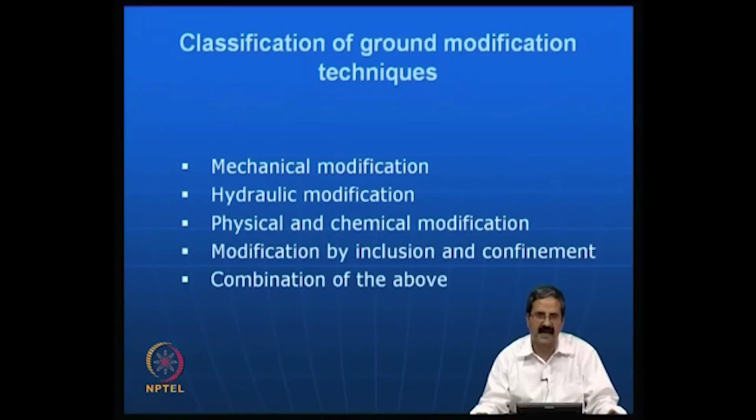The liquid limit will come down to, say, 60%, and the shrinkage limit will increase to 20%. In the first case, the range of water contents is 100 minus 10, which means 90%, and it leads to a lot of settlements, because the soil has a tendency to undergo a lot of volume change because of water content variations.